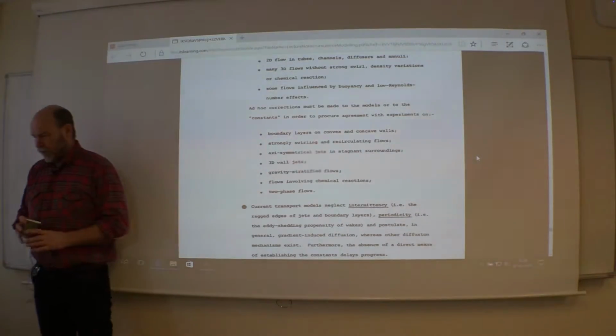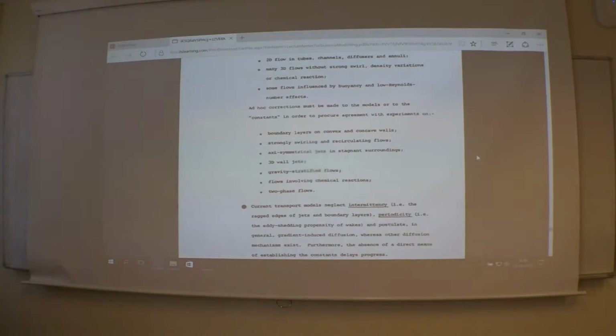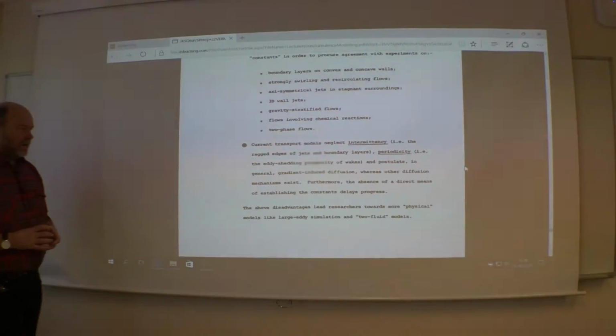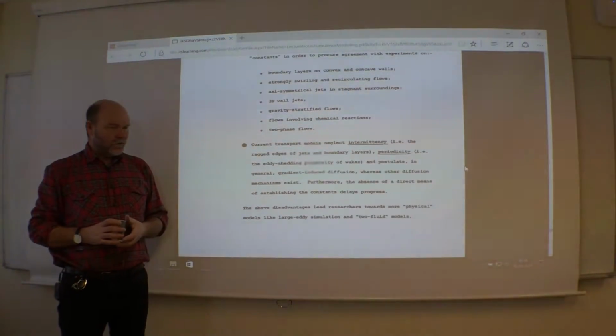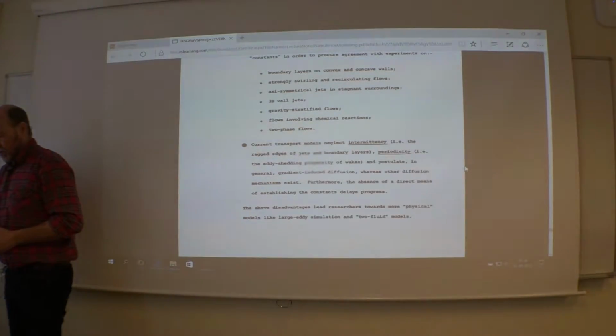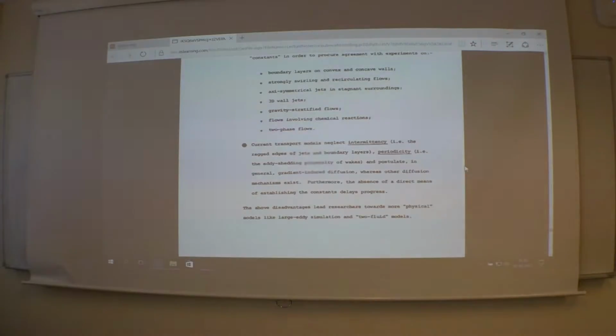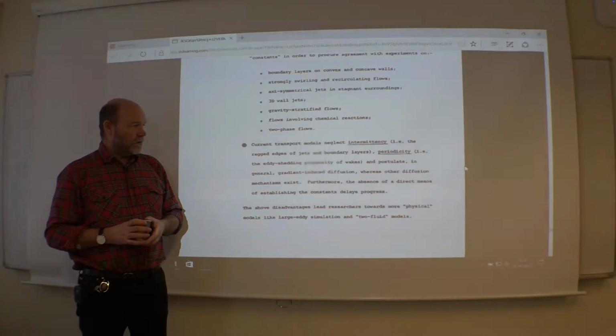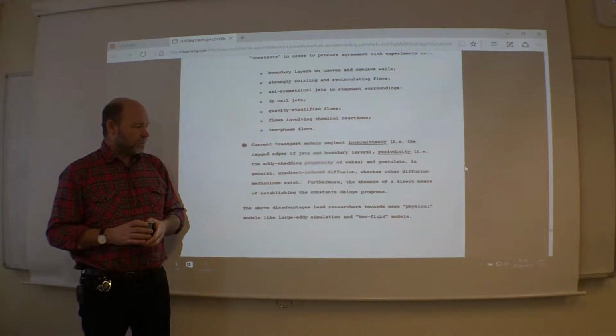Multi-phase, stratified flows, and also when things become laminar in different zones, then they also have a tendency to fail. There typically you need to switch on some low Reynolds number models to handle laminar tendency inside your domain.